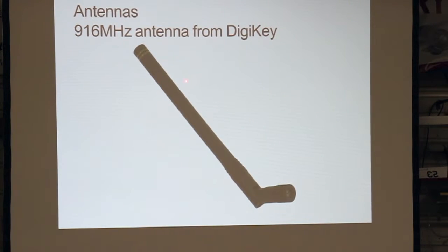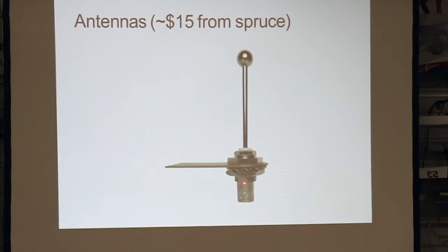This is one of the common antennas. If you want to upgrade or change the form factor of your build, really the antennas that come with the tuner just work really well. These ones are mostly for looks, and it's maybe a little bit more stable depending on how you're building it. It's tuned for 916 megahertz. You can use it for both bands. If you're building a dual tuner Stratux, you can just use 2 of those, or you can use a splitter and just use 1. This is what I'm having installed on my plane.